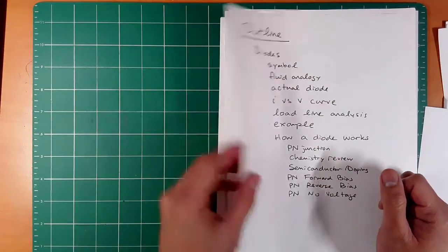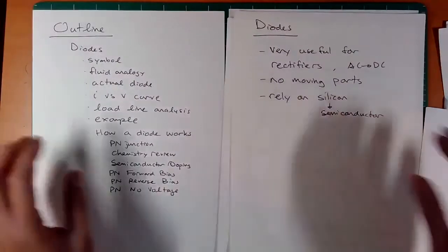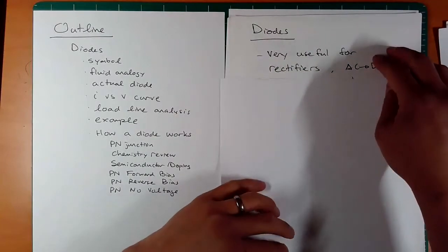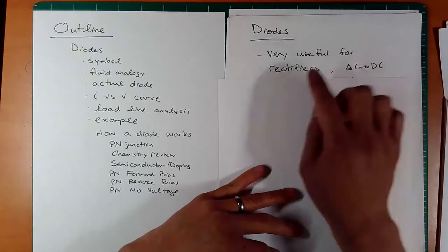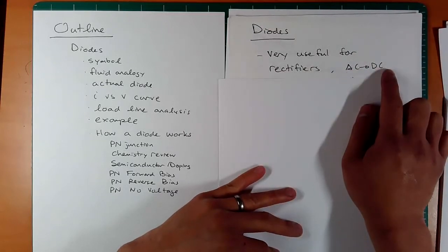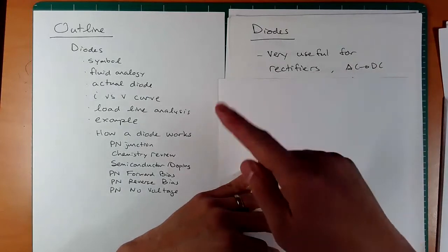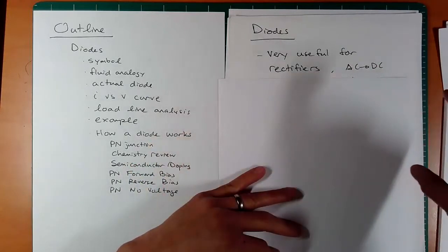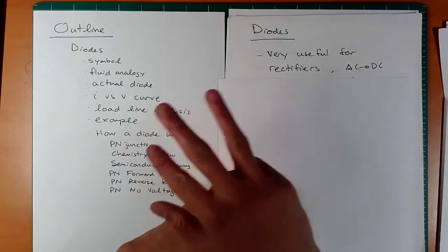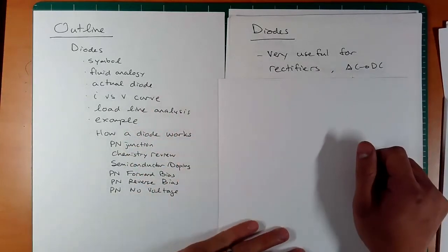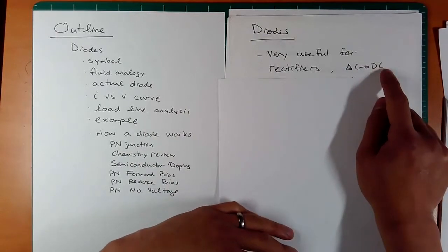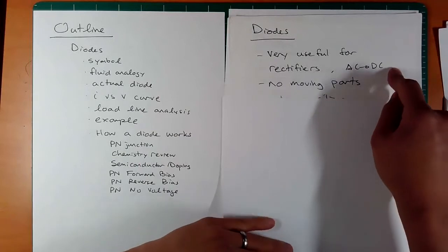Okay, let's begin. So diodes, what are they useful for? Well, one big use in diodes, and especially for power electronics, is rectifiers and converting from AC to DC. So you have single phase AC that's oscillating and you want to have something that's DC, smooth with a capacitor. Diodes are going to be very useful. Or three phase coming in, those three balanced three phase or even unbalanced three phase, and you want to again convert it to DC, diodes are very useful.